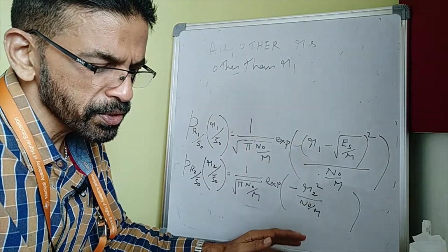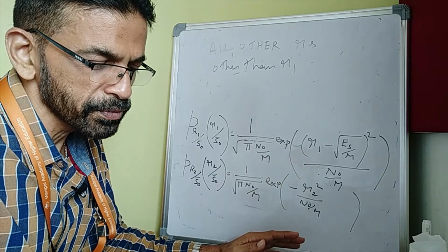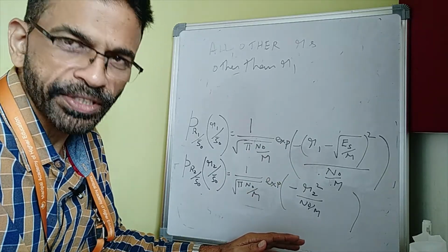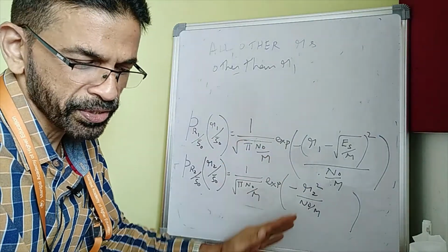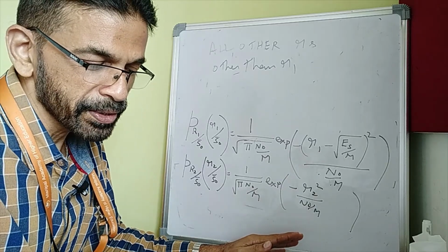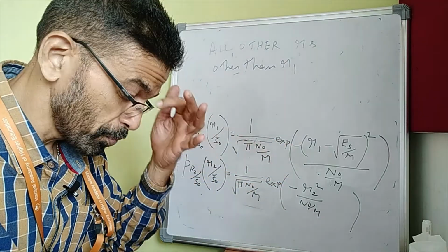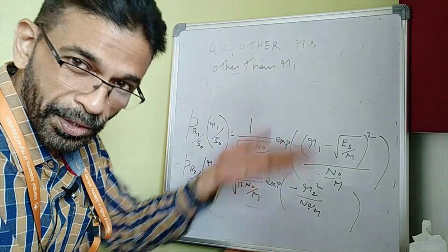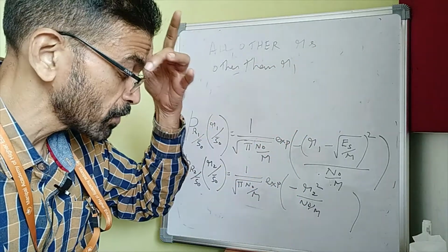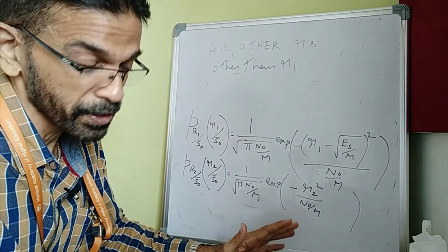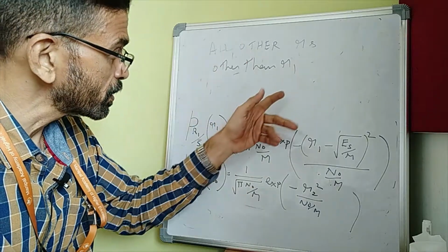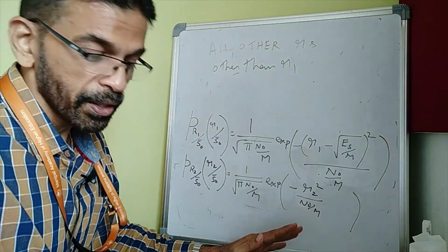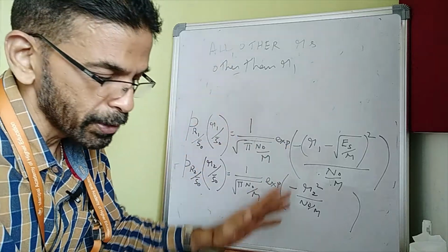We had assumed at the beginning of the discussion that S1T was the transmitted signal, then a correct decision is taken if all other R's except R2 take a value less than R2, or R2 is the largest value. Anyhow, in this case, we have taken S0T as the transmitted signal. So we repeat that a correct decision happens when R1 takes the largest value.